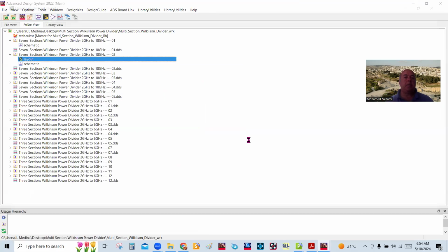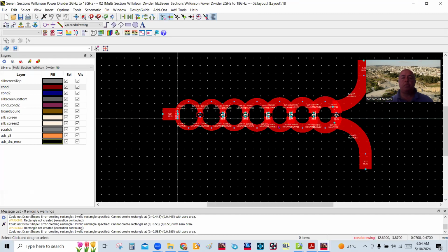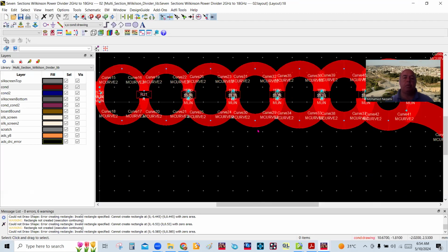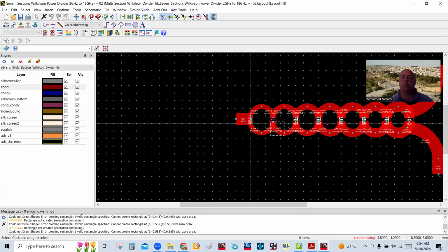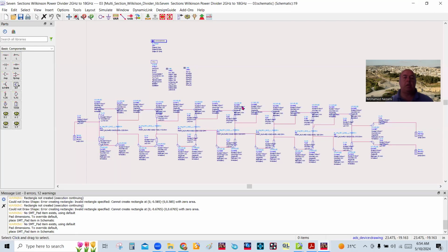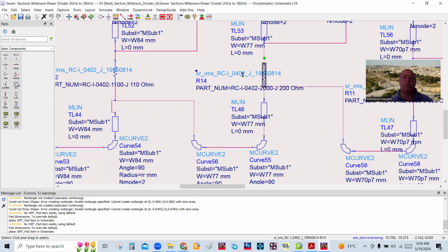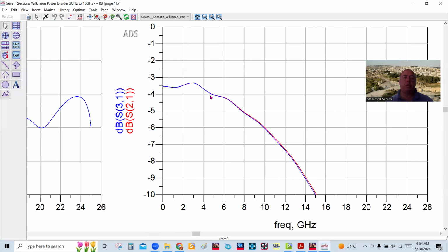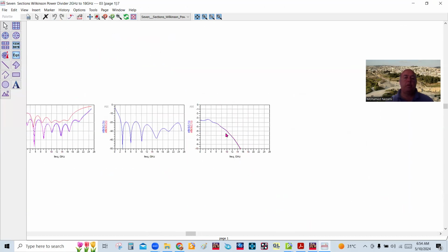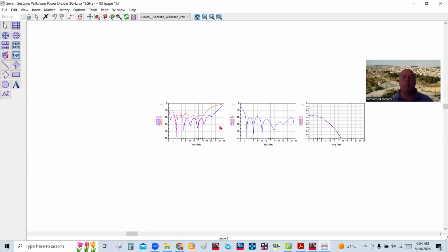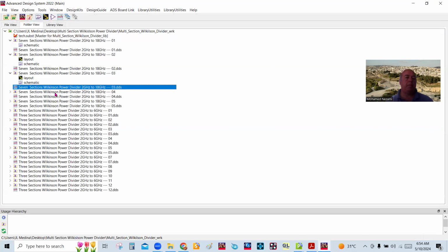Now let's look at the layout. The layout, of course, is right here. So we're very good. We've got all these, and these ones in here we might separate, and everything looks good, okay? Except now, when we stick in these real model resistors, based on these 0402 packages, of course, the response becomes a little bit worse. You can see that the parasitics have really shut this down, and the performance is not as expected, okay?